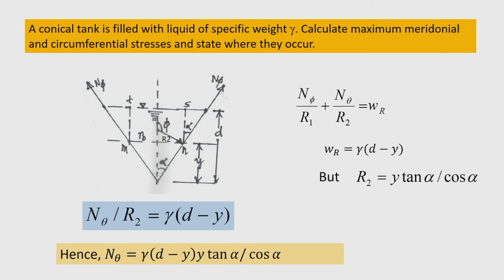For example, we have a water tank which is a combination of cylinder, sphere and cone. This type of tank is generally known as Intze type of tank. Here, in the Intze type of water tank, that is the elevated water tank, you will find that the roof cover is a spherical dome of small rise. Then the tank wall will be a cylindrical shell.